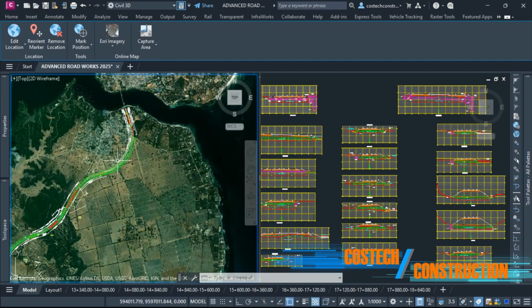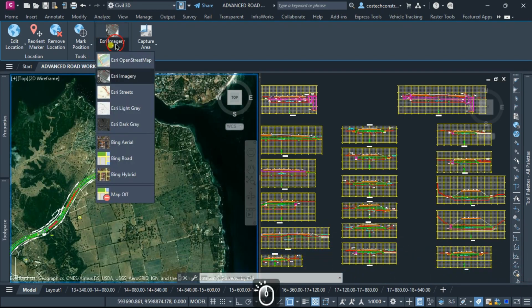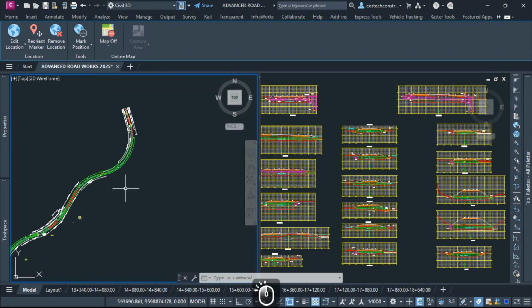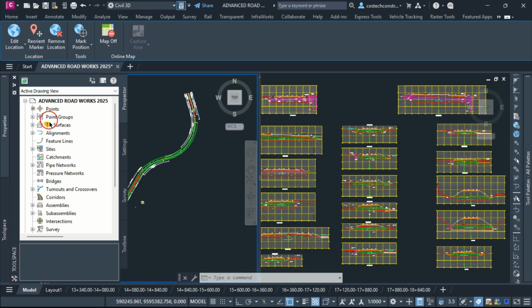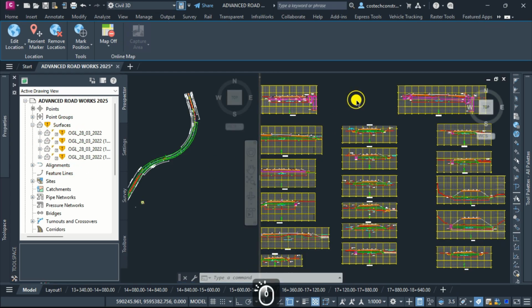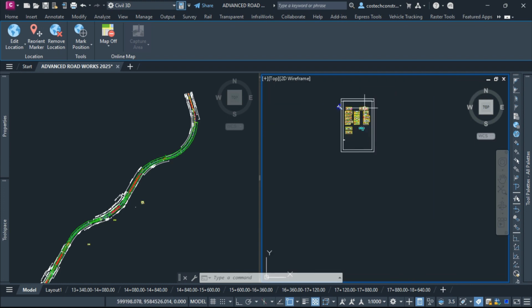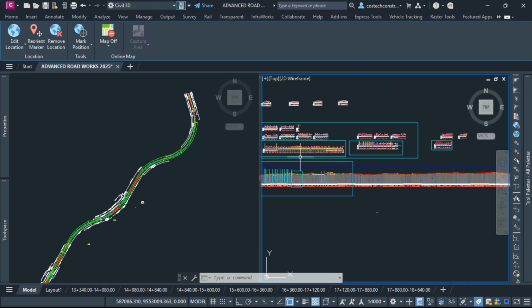I will close the map to discuss other details from here. Then select Map Off. We can go to Tool Space Palette, then expand surfaces. The drawing has referenced surfaces which we unfortunately don't have. We can, however, design both our sewer and road using the drawing profiles provided below.